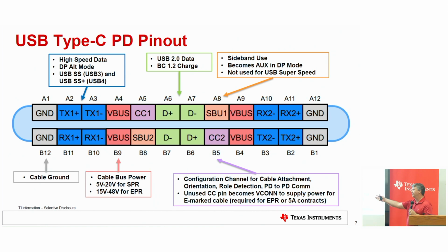And in some tools, we actually have over here an example of a tool that we bought to be able to monitor voltages and current going through the USB cable and to act as a sink, so we can pick different voltage contracts. That one, for example, doesn't handle the flip very well, and you have to have the cable plugged in a certain way. But they should have handled that. You automatically get a flip event knowing that it's inverted. And through our registers and our GUI, you can actually see whether the cable is right side up or upside down.